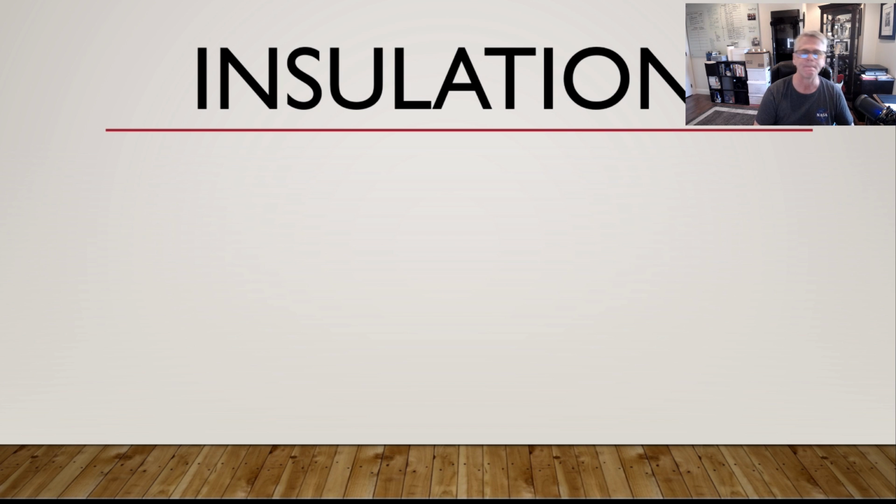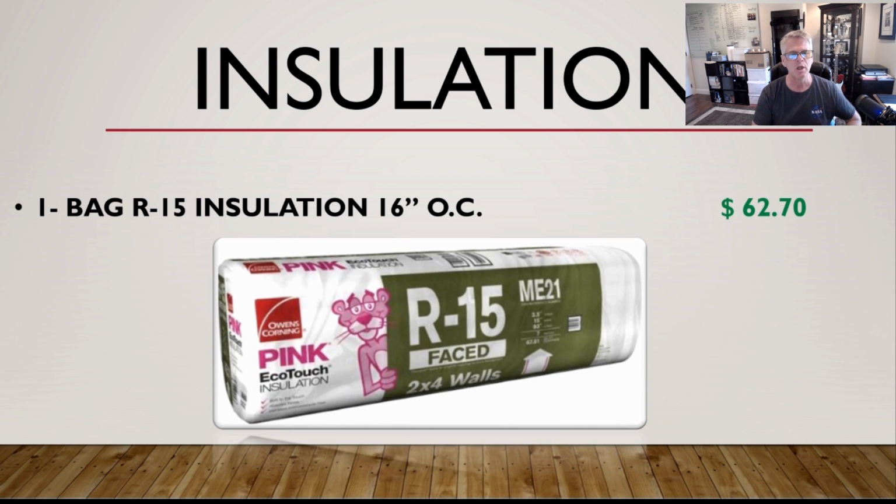$107.50. Insulation, real simple. We use the R15 16-inch on center Owens Corning insulation. Doesn't have to be Owens Corning, but R15 faced insulation will go in all the wall cavities. If your bathroom's bordering a storage room, the storage room will be cold. You want that wall to be insulated. We consider that an exterior wall, but we also insulate the rest of the bathroom walls just for a sound buffer.